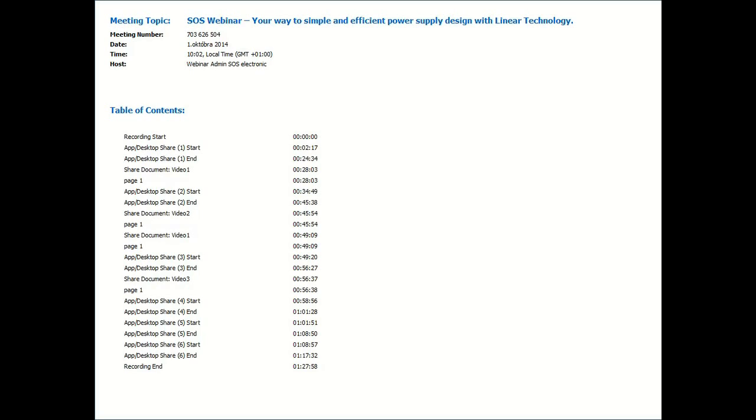But this one is not a boost. This is a step down converter. So the answer is no, you cannot, because it takes the voltage and steps down on the output. So we should look for a micro module which has a possibility to boost the voltage.